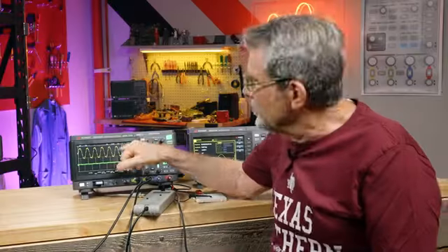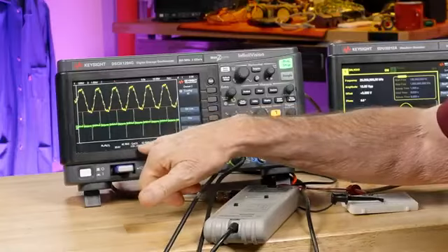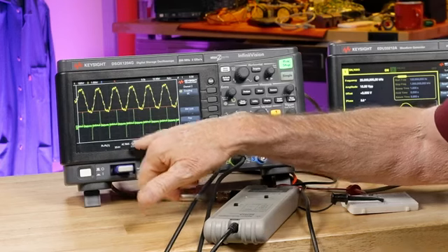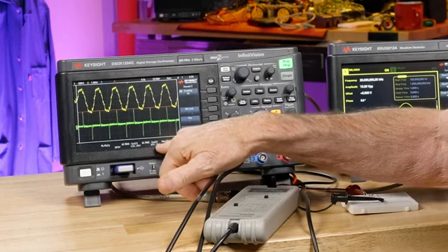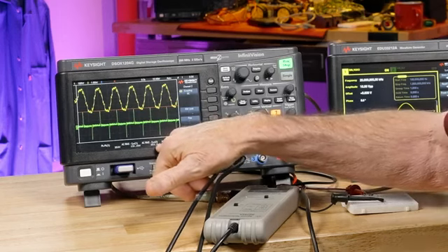Now that we've been able to capture and display input voltage and current of our function generator, let's pick up where we left off in the last lesson and now measure the power consumption of this function generator. So here's our AC voltage input signal. It's measuring about 120 volts RMS, and the current, remember it's pulsed, it's measuring about 360 milliamps.